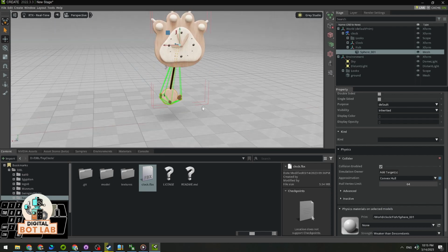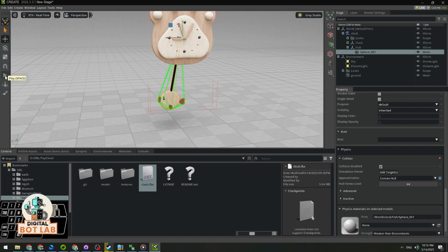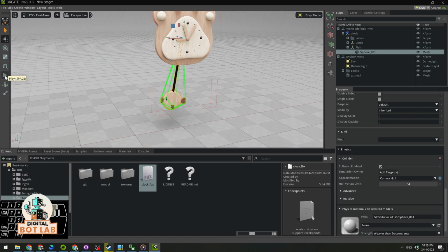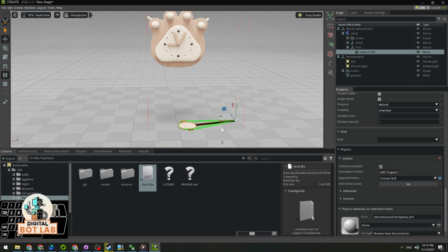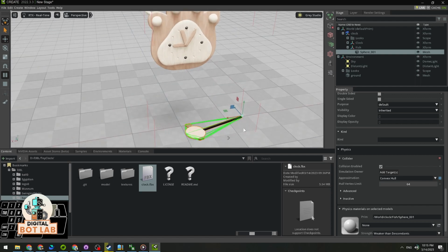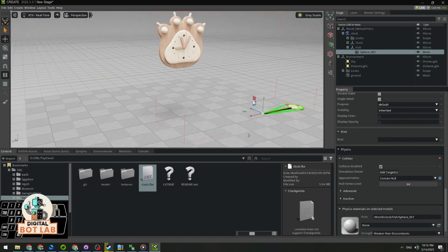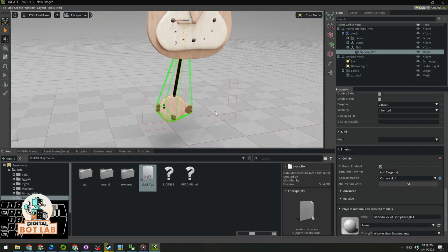And if we click play here, the scene will be simulated automatically. Let's see what will happen. And you can see that since the rigid body of this object is enabled, it drops directly to the ground. And if we hold the left shift button and use the left mouse button to drag it, which will apply a force to it, you can just play around with the scene to see the behavior of this rigid body. If we click stop here, we'll go back to the original point, which is very good.